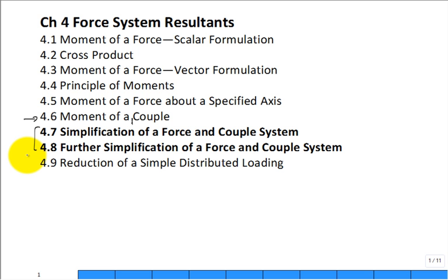So you can simplify a more complex force system, we saw that before, by having just a single resultant force. You can do the same thing for moments. So the moments, you can have an equivalent single couple moment applied to the body or object at a location, which gives it the same tendency for the body or object to rotate. Just like the equivalent force had a tendency to translate the object, the resultant moment would be for the body to rotate about 3 of the axes, just like the force translates along 3 axes.